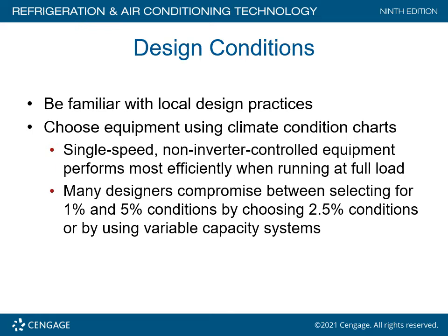We are utilizing today constant torque ECM type motor technology. The idea is we ramp up, ramp down based on the loads, and by doing that, we can get a better handle on heat removal. Mini splits have done this for years, and they work fabulous. They're great. I have no issues with them.